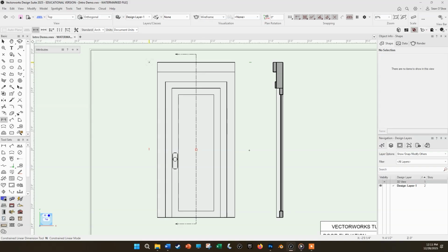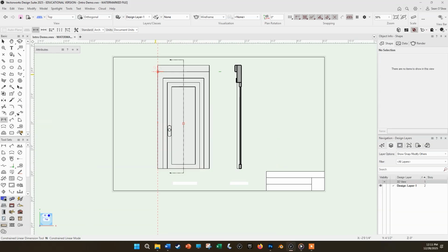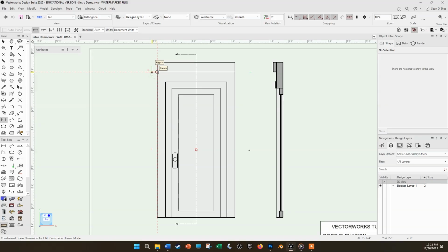do this. So zoom in or out with your scroll wheel until you can see the whole height of the door flat. Now you can zoom and pan in the middle of setting a dimension, but it's just easier if you don't have to do that while you're starting. So make sure you can see the top and bottom of the door.